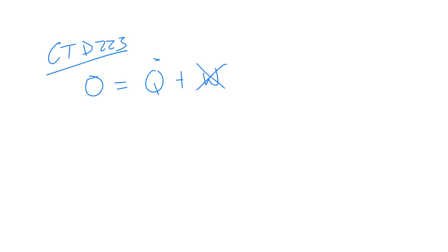So what we are doing is in fact the CTD approach. This relates to your CTD pre-knowledge, where we said, okay, we know that our energy balance is 0 on the left-hand side, because we're at steady state, equal to Q. We are going to neglect all work terms, so all shaft work terms are negligible. We're not driving turbines or pistons or whatever, plus energy that's in with mass, and we are only going to consider enthalpy, energy leaving.